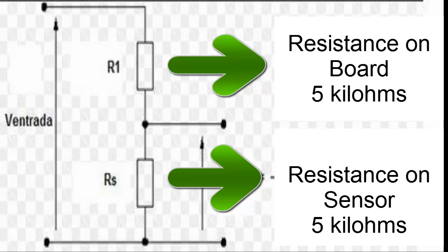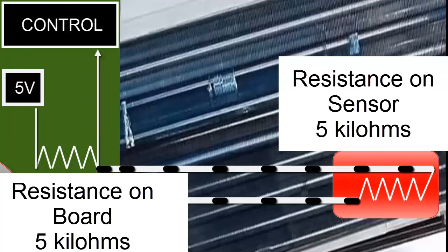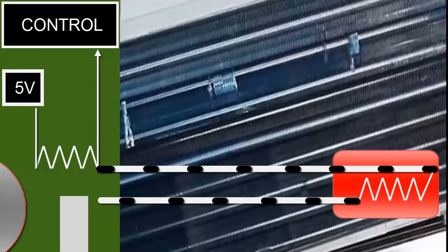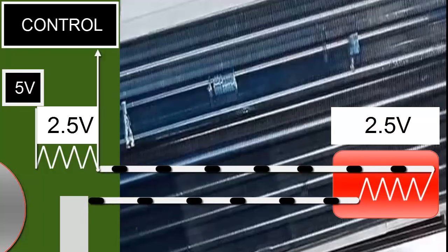3. For example, in this voltage divider circuit, both resistors have a value of 5 kiloohms and are powered by the electronic card with a voltage of 5 volts. 4. At 25 degrees Celsius, the 5 volts from the regulator are distributed with 2.5 volts in the first resistor and 2.5 volts in the sensor resistor. This happens because, at that moment, both resistors have the same value, which is 5 kiloohms.